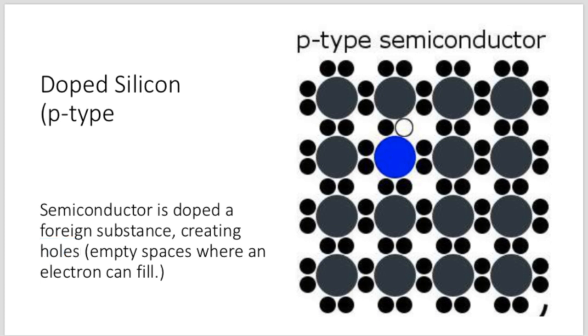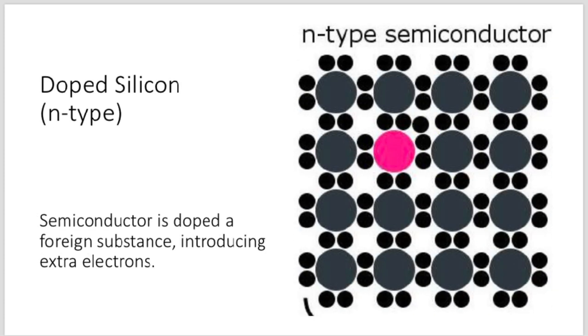Now, because we are reducing the number of electrons, remember an electron has a negative charge. If you take away a negative charge, or you reduce the amount of negative charge, meaning to say there are more positive charges, so these holes act or behave as a positive charge. So hopefully it's beginning to make sense what is actually happening here.